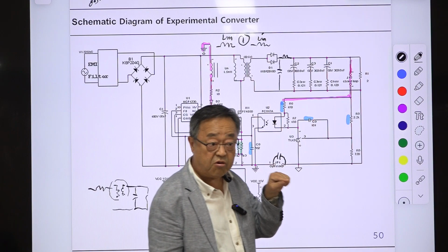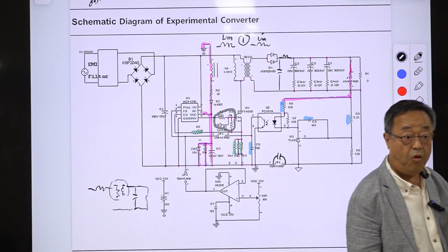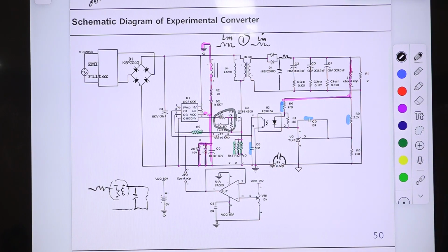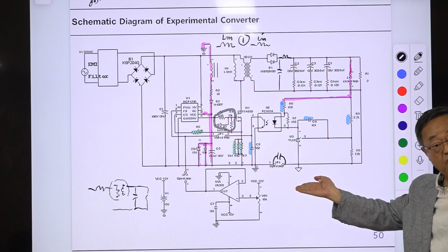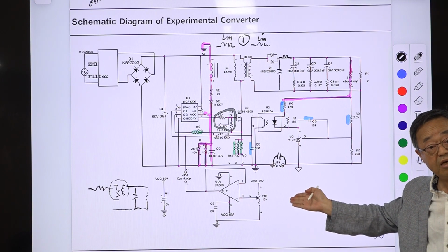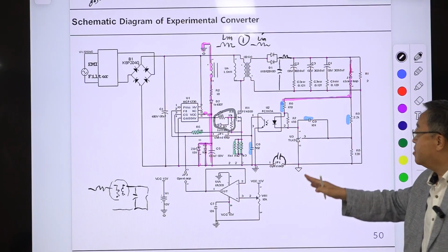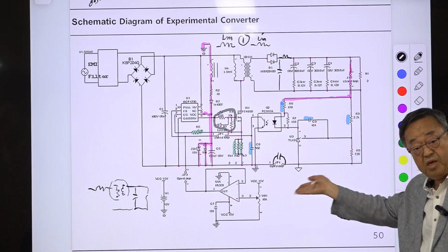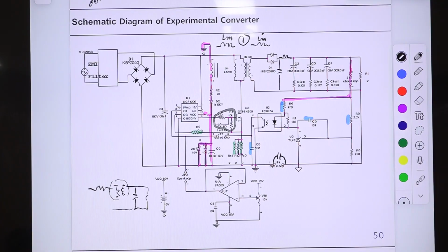This is an open circuit because the C is so small. But for high frequency noise, even though C is very small, this is connected, and the high frequency noise does not have much power. Then the EMI problem will be reduced. You can overcome the EMI problem. So practically they are connecting this.